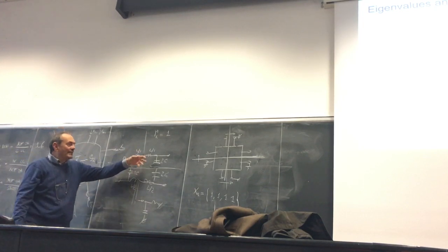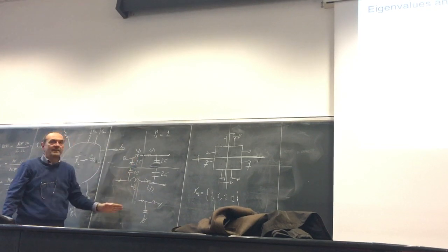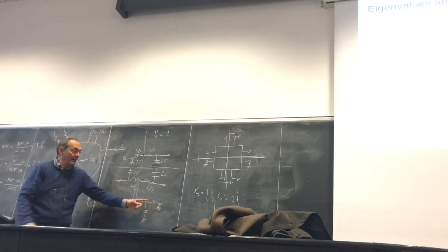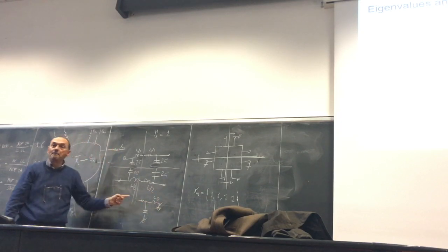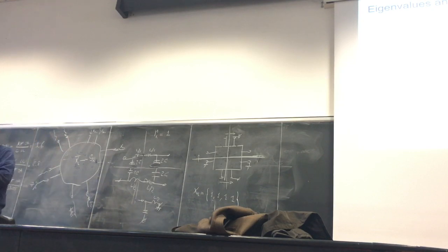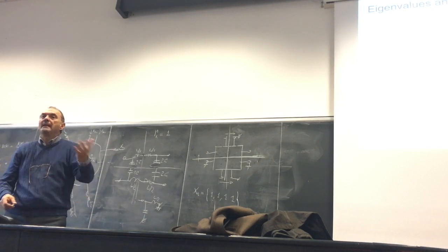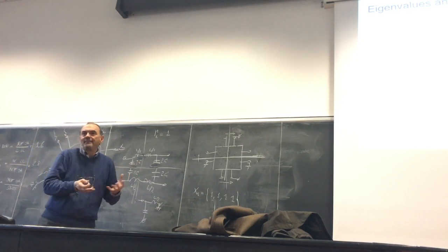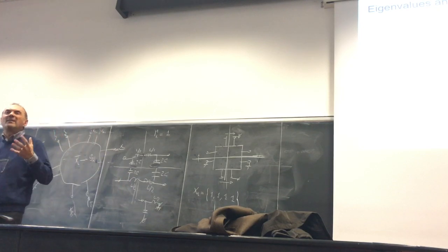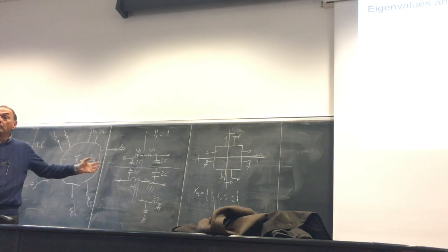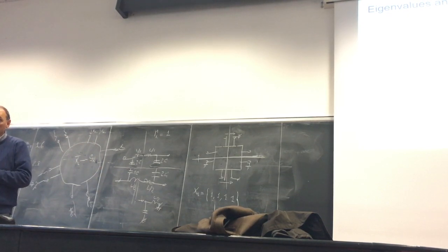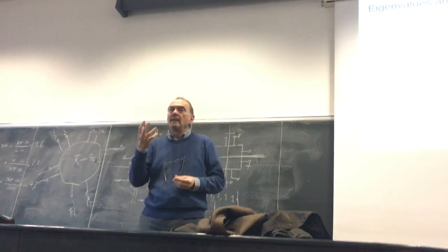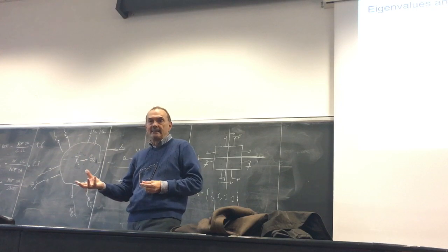And then you can try all the other combinations. For instance, if this is a short circuit and this is an open circuit, the difference is this one. And then at this point here, I have L divided 2, and the impedance is L divided 2 multiplied by omega 0. And gamma will be the corresponding reflection coefficient. And so on for all the others. So it's trivial to get at the end the eigenvalues of the network once you have identified the eigenvectors. The last step is how to relate the eigenvalues and the eigenvectors to the matrix.